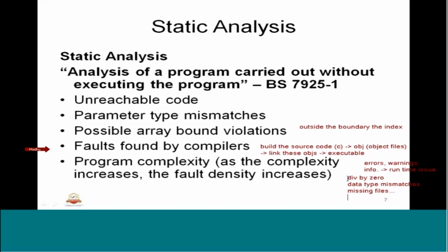Of course, MISRA errors. If you have enabled the MISRA check while doing the compilation, it will throw them too. You can have severity and normal sorts of rules. So it is better to clear up all these types of errors. Severity errors definitely we have to clear up, and normal errors also sometimes lead to some issue while running the program. So all these have to be clearly analyzed and reported. That is the objective of static analysis with the help of compiler reported faults.